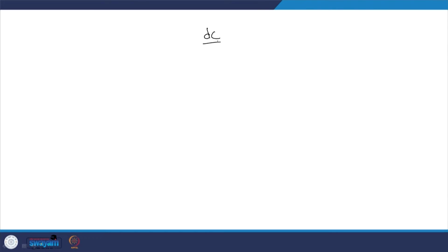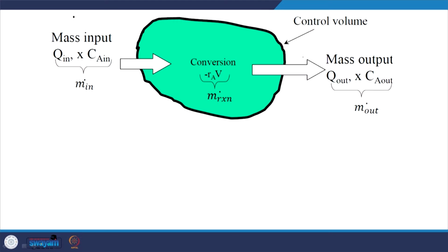In that context, we looked at the fundamental mass balance equation, and we see that we neglected diffusion and dispersion. So, the accumulation term plus u dc by dx, which is due to advection, right. Concentration change with distance. Why is this? Due to advection, let us say, is going to be equal to rate of formation minus rate of loss of the particular compound, let us say. This is the fundamental mass balance equation, neglecting diffusion and dispersion. So, we will try to understand the mass balance in the usual way too.